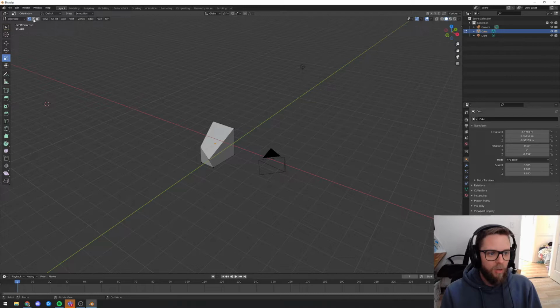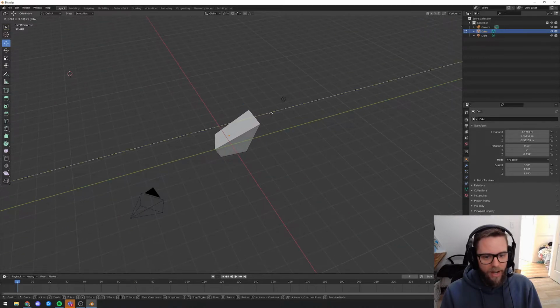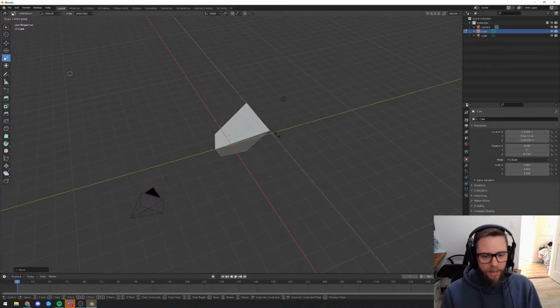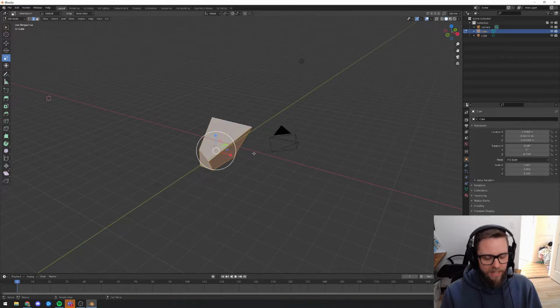The next thing, if you have a look up here while we're in select mode, is edge select. Now edge select will actually let me select edges rather than vertices. I can select a line that connects from one vertex to another vertex, and I can move that entire line around. I could also scale it to lengthen that line or shrink that line. A to select all, double press A to deselect everything.